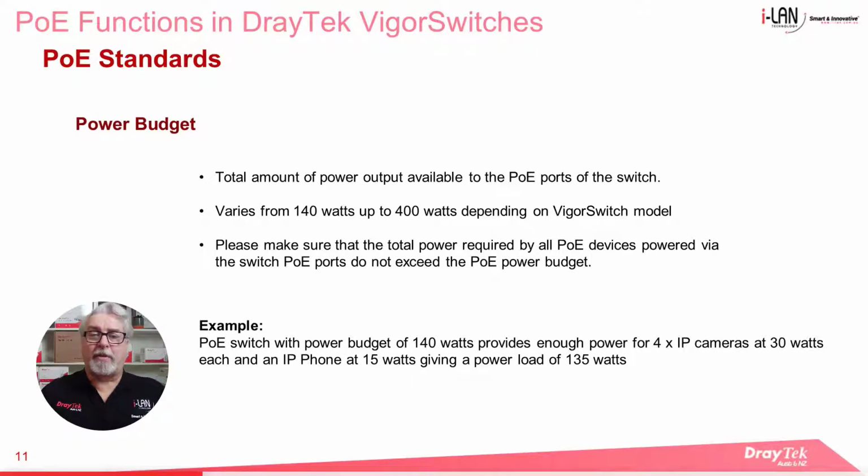For example, a PoE switch with a power budget of 140 watts can provide enough power for 4 IP cameras at 30 watts each and an IP phone at 15 watts to give a total power load of 135 watts.